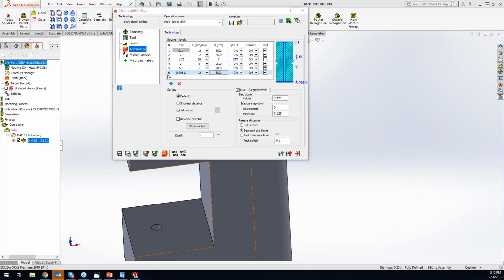let's say I get down to the bottom, and instead of, as it's retracting out of the hole, spinning still clockwise at 3,500 RPM, maybe I want to just switch that over to counterclockwise at like 500 RPM. So it's doing a simultaneous, as the Z is going up, here I'm holding my hand up, spinning it. It's doing a reverse feature going up out of that hole for you guys. And then here's your dwell.